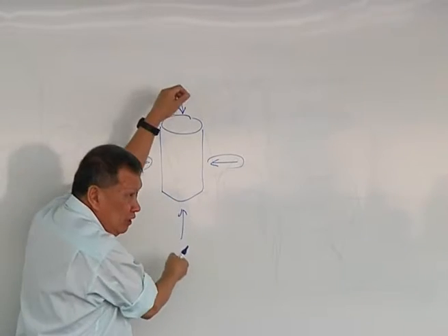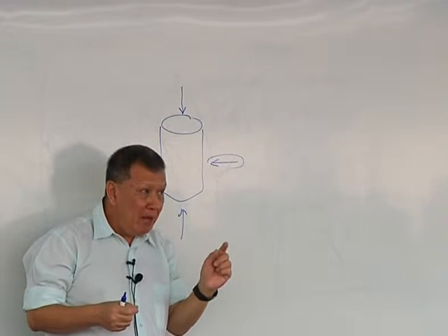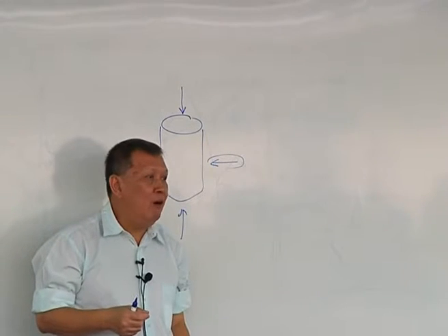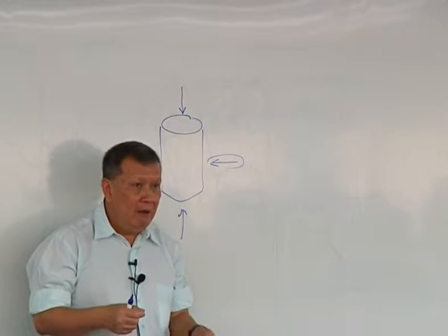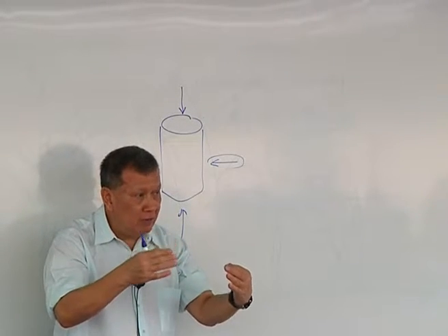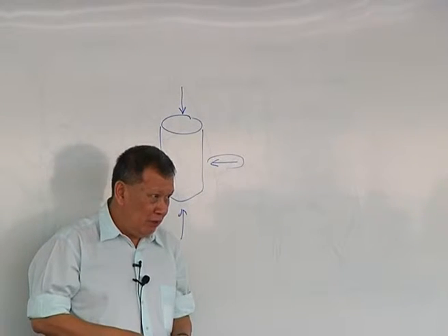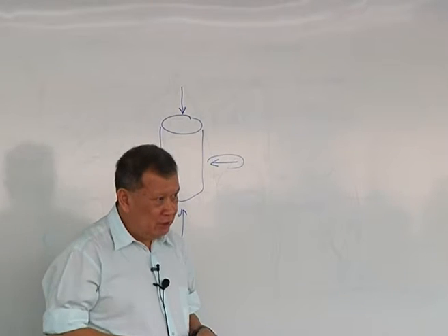So basically, what it tells you is that this is an example of how the shear stress works. You can be unloading this face, and you may think it's going elastic. But actually, there may be an elastic region, but it's going to be very small. And in fact, your shear stress is increasing, the deviator stress is increasing. So as a result, the whole thing is going to come out deforming plastically, because it is actually driven by shear stress.